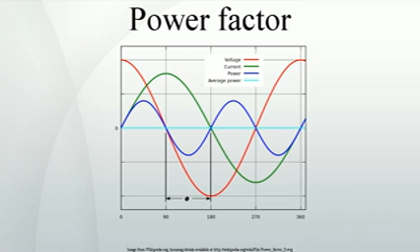Digital instruments can be made that either directly measure the time lag between voltage and current waveforms and so calculate the power factor, or that measure both true and apparent power in the circuit and calculate the quotient. The first method is only accurate if voltage and current are sinusoidal. Loads such as rectifiers distort the waveforms from the sinusoidal shape.